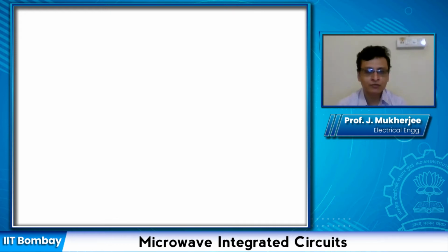What would be the value of the input reflection coefficient? Now in this part, we are going to do the opposite. That is, given a certain input reflection coefficient, how can we find out the values of the characteristic impedances of the various sections of the multi-section transformer? So we are trying to find out the values of Z1, Z2, Zn of the multi-section transformer.